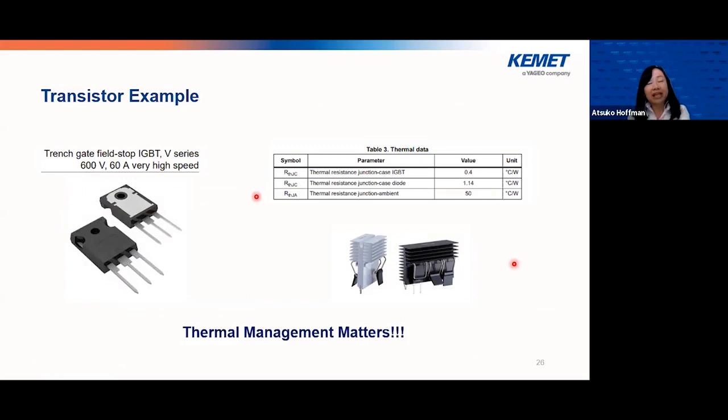Either it could be adding a heat sink, increasing traces to pull the heat out, or active cooling. Any kind of thermal management helps. And these factors influence an MLCC's ripple current, just like the transistor.